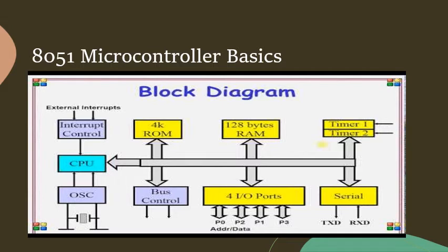The 8051 microcontroller is an 8-bit microcontroller, that is, the data bus of the 8051 both internally and externally is 8 bits wide. It is a CISC, complex instruction set based microcontroller with Harvard architecture, that is, it has separate program and data memory. Since the basic layout of a microcontroller includes a CPU, ROM, RAM, etc., the 8051 also has a similar layout. The following image shows a brief layout of a typical 8051 microcontroller.